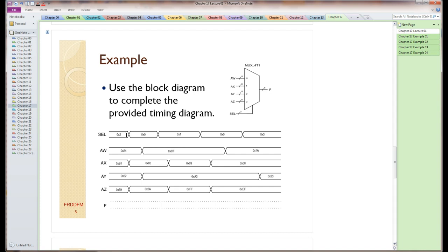The examples we did, and the circuit we described as being a multiplexer, is extremely simple. It works well with buses also. The issue here is you certainly wouldn't want to design this the way we designed it before, because it actually has 34 inputs. That's going to be a very large table. You're just not going to want to design that circuit. But it's still the same selection criteria, and I'm going to mark when these select variables are changing with vertical lines so I know what's happening here.